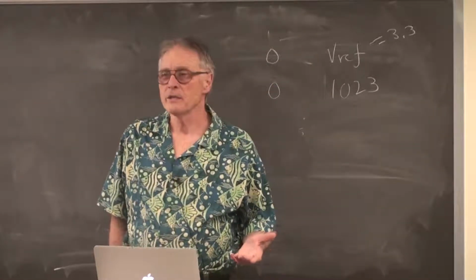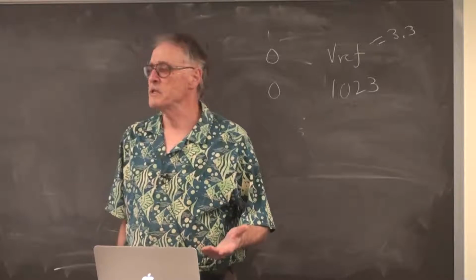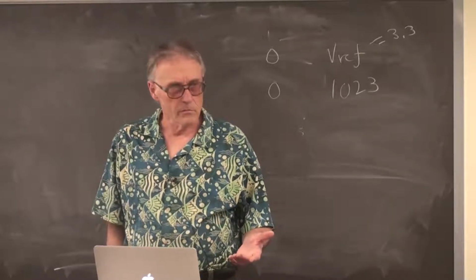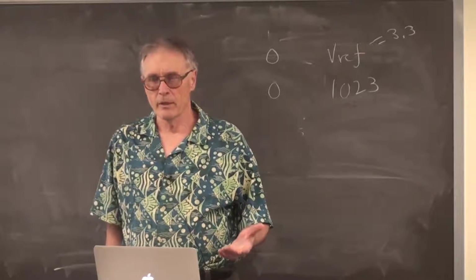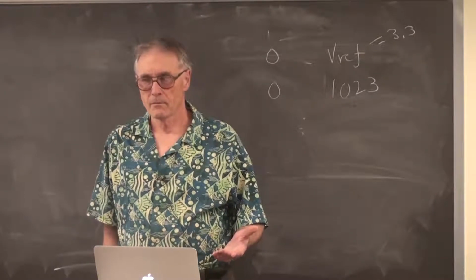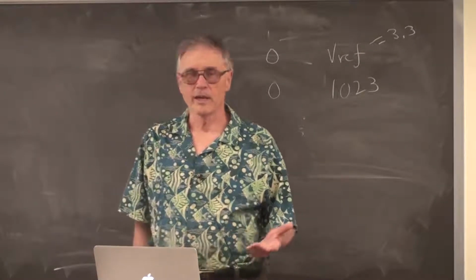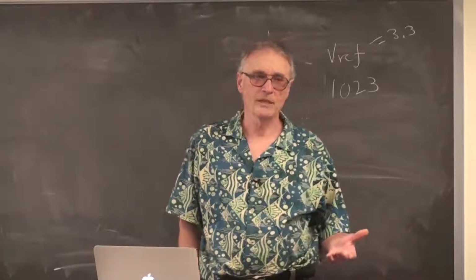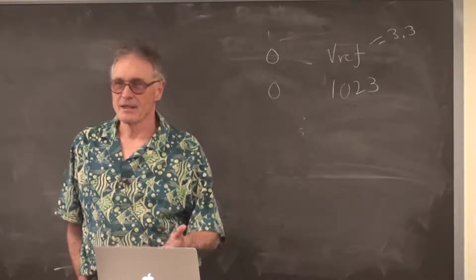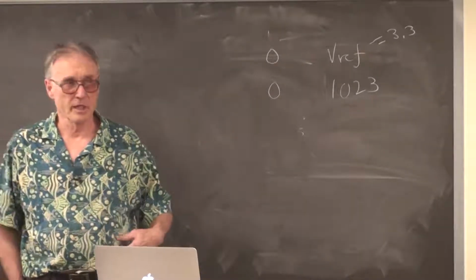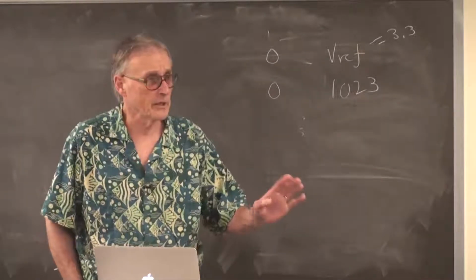So you can turn it around and ask, at what point does speech become unrecognizable? If the sample rate is high enough, you only need 1 bit. At 8 kilohertz, you can actually understand 1 bit speech. It sounds pretty robotic, pretty nasty, but you can understand it. 4 bits is completely understandable.